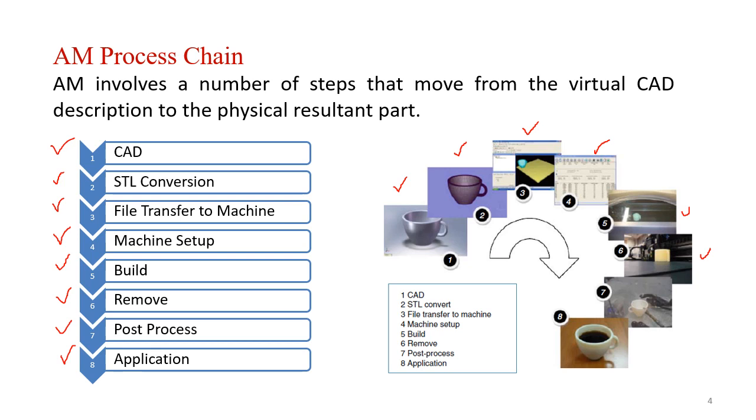Next comes the post processing. Under post processing, the finishing or surface cleaning or support removal or sacrificial layer removal is taking place, and if we require to apply paint and give aesthetic look, that happens in case of post processing. Last one is the application, and you are using the product for the end to how it has got formed or how it is going to be coming out. That is also one of the step in case of additive manufacturing process chain.